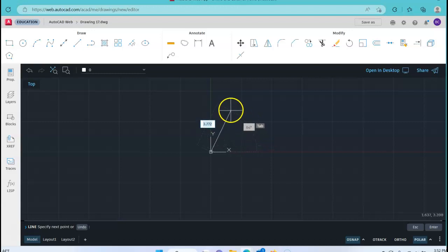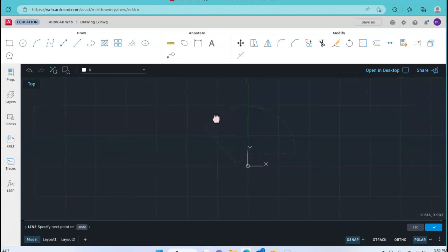In this case, the first line is going to be a 1 inch vertical line. So that'll be 1, tab, 90 degrees, and I place that line. My second line, now in this case, where before we weren't really given the angles, here we are given the angles. So I know the line length here is 3.5. I'm going to hit tab. Now I've got to figure out what this actual angle should be. Well, it's given off of the vertical line, which is 90, and then we add that 60. So 90 plus 60, this will be a 150 degree angle, and I'll hit enter.